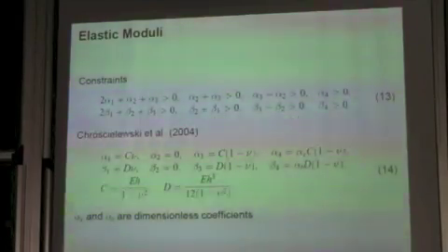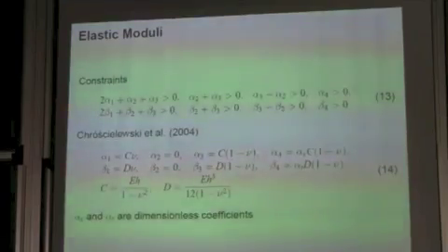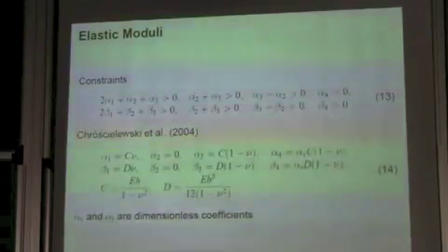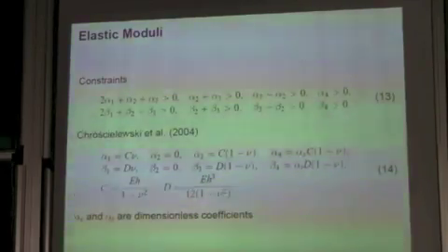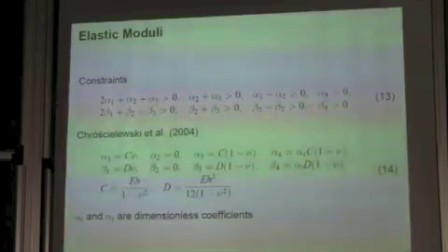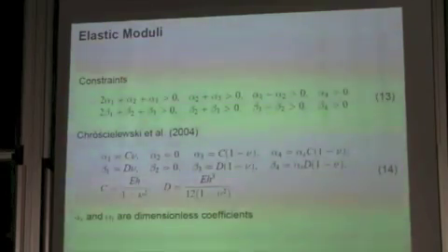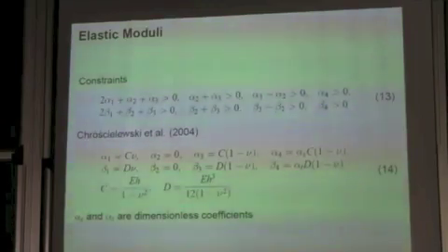The exception is alpha 4 and beta 4 properties, because now we have the influence of 2 additional dimensional coefficients. So one of these is well known as a shear correction parameter, but in this case it is not a shear correction, it is related to some type of behavior. And you see here alpha S, this is similar to the shear correction in the classical or non-classical theories, and alpha T is related to the torsional behavior.